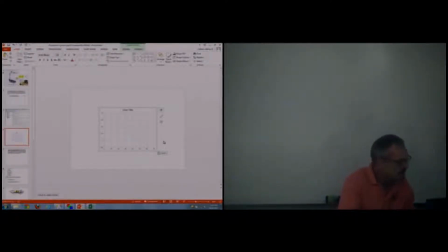Your gamma WS, which was that stage 2, 3, or the GP? Well stream. For recombining the oil and all the gases together, once it's back in the reservoir, that's the gravity of the fluid compared to air. The specific gravity of the well stream is compared to air. So numbers greater than 1 mean it's denser than air, and numbers less than 1 mean it's lighter than air.